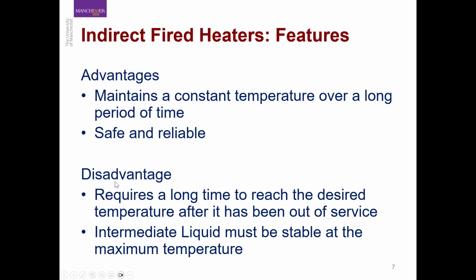A disadvantage of these kinds of fire heaters is that they require too long to start. Because, again, you are using a liquid that has a very high heat capacity, before you reach the desired temperature, you have to heat your system quite a bit, because you have to increase its temperature to the desired level, and it takes very long due to the high heat capacity.